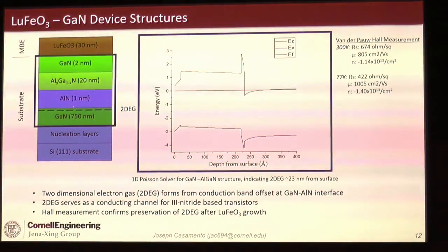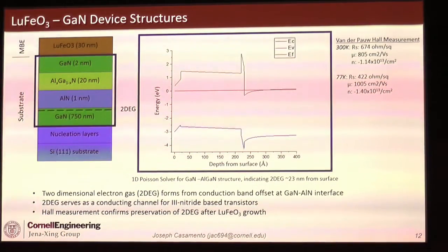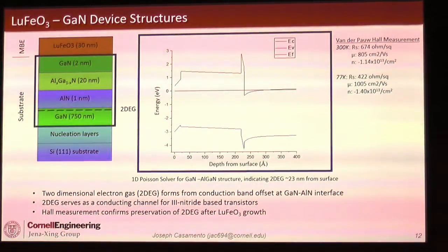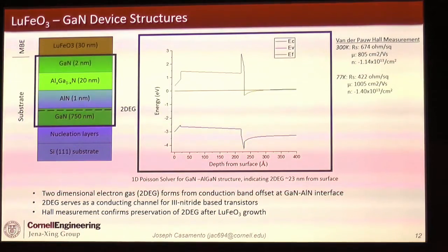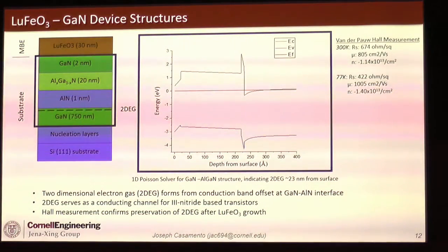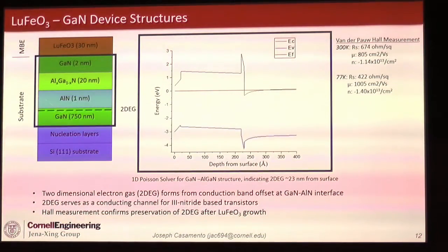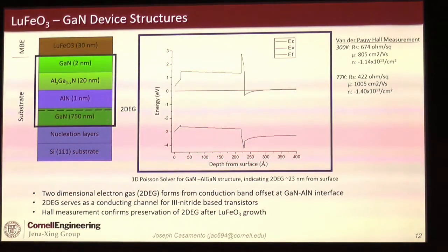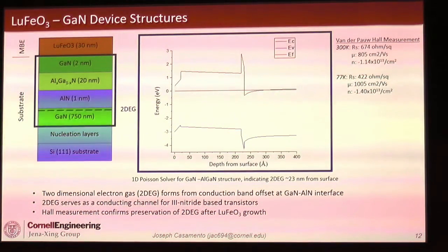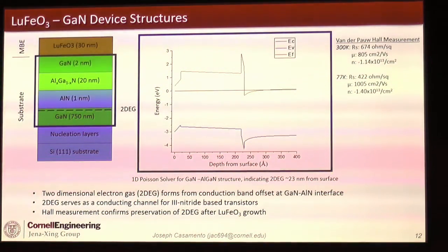And the one thing here we were hopeful for is that leakage mechanisms in ferroelectrics are known, and so you essentially have 22 nanometers of an insulating barrier between your channel and the carrier concentration that you want to modulate in the actual surface of your ferroelectric. So that's something that we thought might be beneficial.